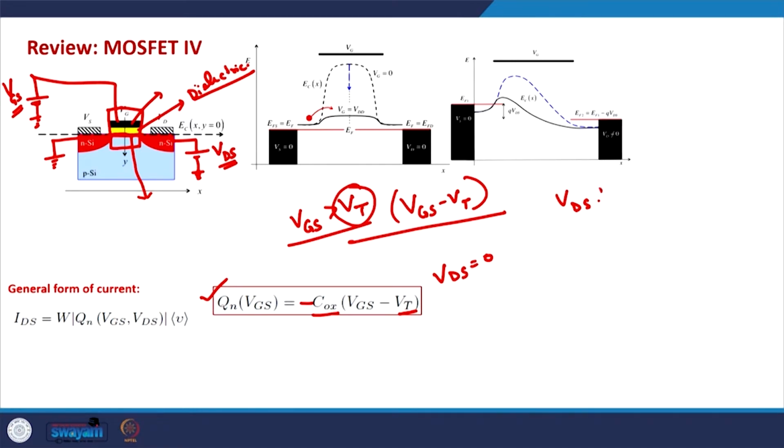So, when there is a VDS voltage, the potential at any point in the channel will also be affected by this VDS. As we know, on the source side the voltage is 0, on the drain side the voltage is VDS, sometimes written as VDD, and along the channel the voltage drops from 0 to VDS. At any arbitrary point in the channel, where the channel direction is the x direction, the voltage can be written as Vx. Okay.